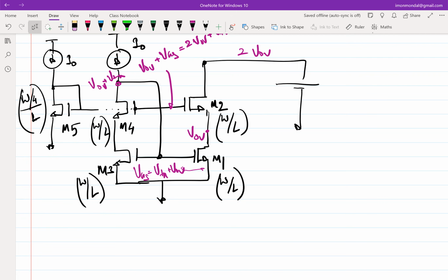Okay. So generally, if you have to consider channel length modulation, then you have to figure out which transistor is setting the current. Typically, the transistor whose gate can swing independently of the source sets the current, right? If the source is fixed and the gate is swinging, that essentially determines the current. In this case, that is obviously M1 and M3, right? So that is one way of saying it, but this is again a current mirror.